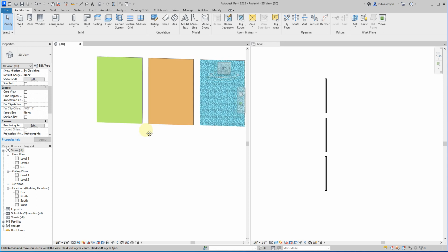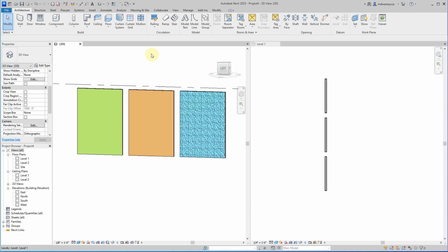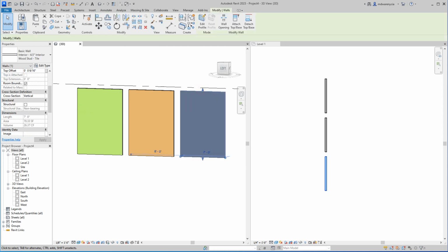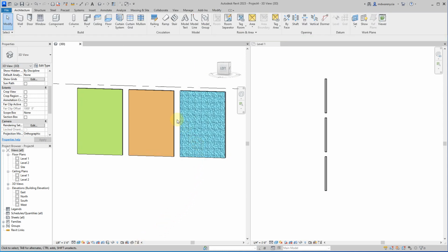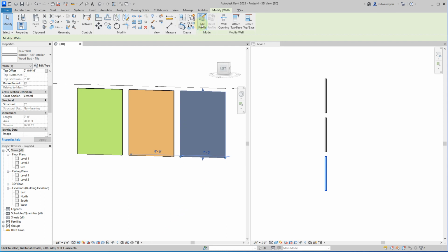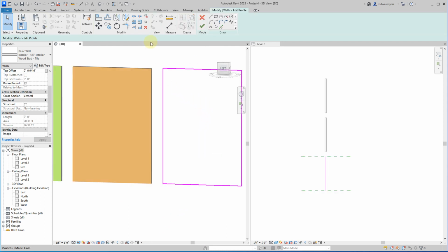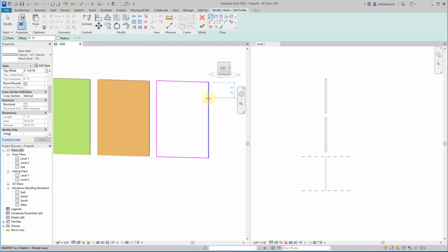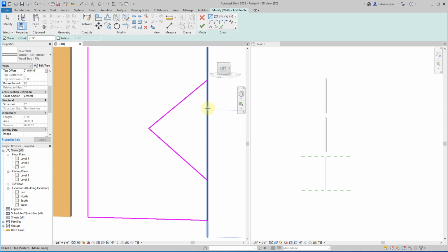Wall profiles is one other way that you can edit things. Earlier, when I showed you guys doing floors and ceilings, I double clicked and it brought up a weird menu. But what you can do to walls is you can click on this edit profile, and you can actually kind of manually put in holes in things. It's a super cool feature of Revit that exists. So if I go through and I do this,